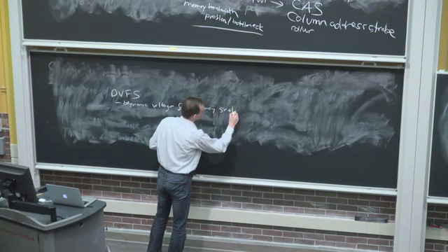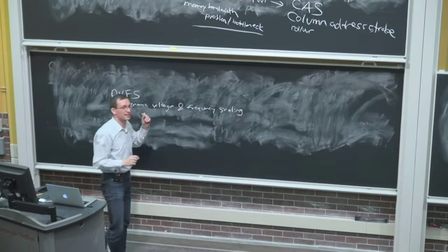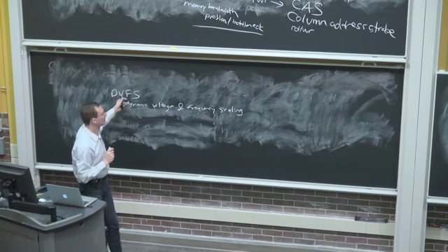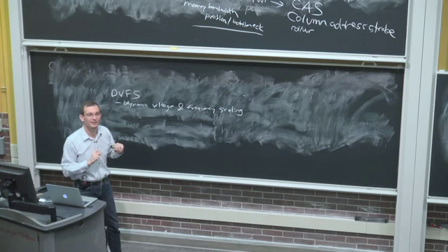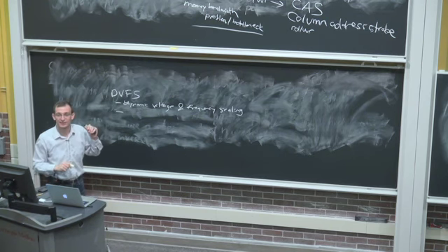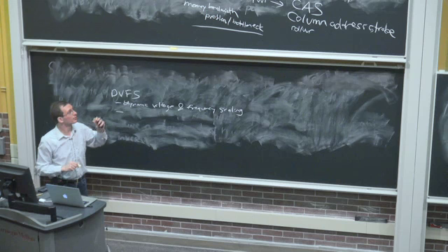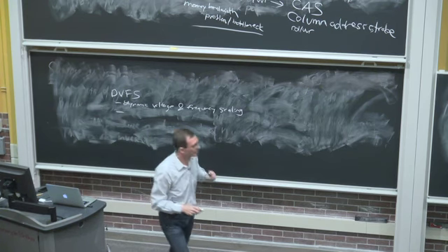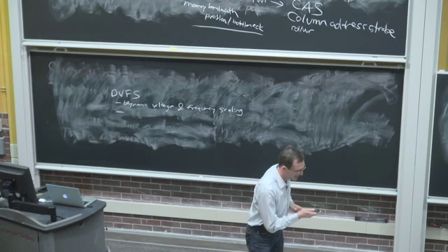And the idea is, if a processor doesn't need to run at the maximum frequency, why don't we reduce the frequency dynamically, such that the clock doesn't need to go up and down as fast, right? Now, what does this do? This saves power. You could do a similar thing at the memory controller also. But maybe we can go into that if we get a chance to talk about power.